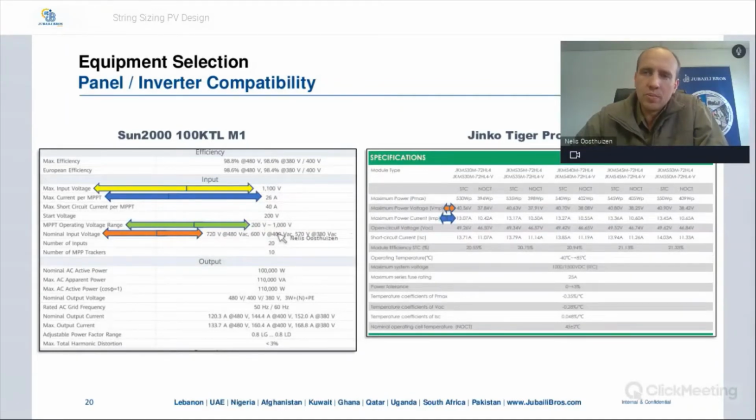If you look at your solar capacity factor in your early mornings at your lower voltages, the lower this value of the MPPT, the earlier the inverter will switch on. And the greater this value of the MPPT, the later it will switch off. So that's your voltage range on the MPPT. But again, when we look at the string design or the number of modules per string, we'll go into more detail on this one.